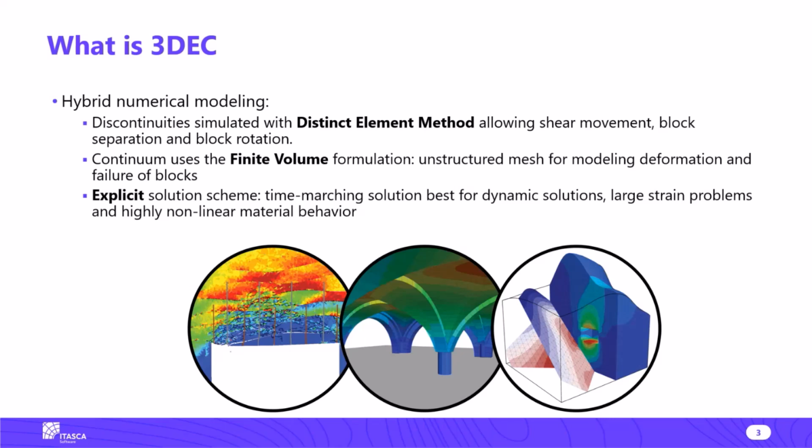So the discontinuities are simulated using the distinct element method so that we can look at the shear movement and separation and so on between the pieces. The pieces themselves may be deformable, and we use the finite volume formulation to calculate the displacements and stresses in the individual pieces. And this is the exact same approach that is used by FLAC and FLAC3D.